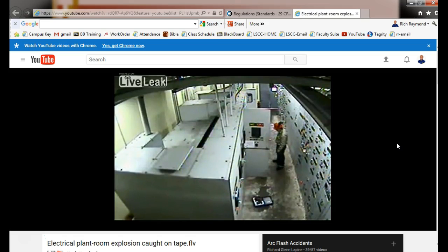But this is racking breakers. For one thing, this was silly because you see that hole in the wall. You see that hole right there in that door? You know what that hole's for? To rack that breaker with the cabinet closed. They're racking this breaker with the door open. And one guy's lucky, the guy that's racking it right now. Basically, it's a screw gear. They have a thing they spin, and it racks it and moves that breaker in.